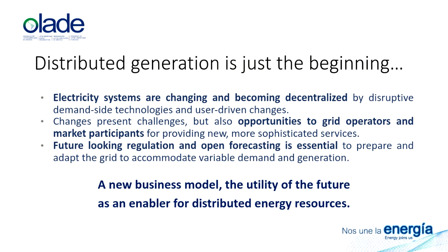For example, in demand response research, in many cases they use thermal inertia to store energy in a building instead of turning on the boiler or the HVAC system. You might heat up a little bit before, when electricity or energy is cheap, and then keep it warm but turn off your boiler.